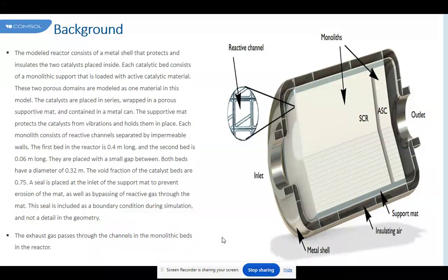metallic substrates are again superior. However, for the case of front-end ignition, ceramic converters may lead to lower cumulative emissions at lower inlet gas velocities, while the converse is true at higher velocities. It is shown that the transient heating time, and hence the cumulative emissions, decrease with decreases in the channel hydraulic diameter and thermal capacitance of the substrate, but are not monotonic with the inlet gas velocity. We present mathematical analysis and simulations to support this conclusion.